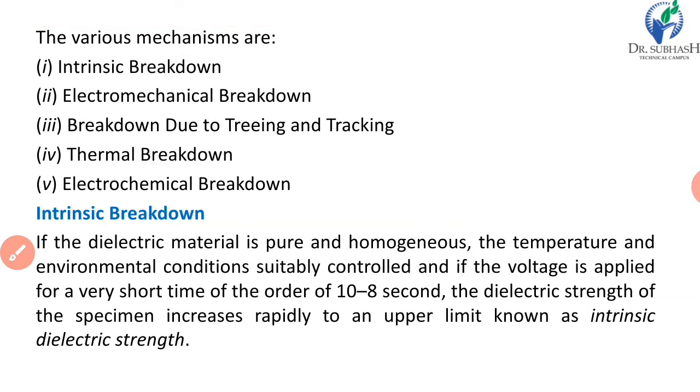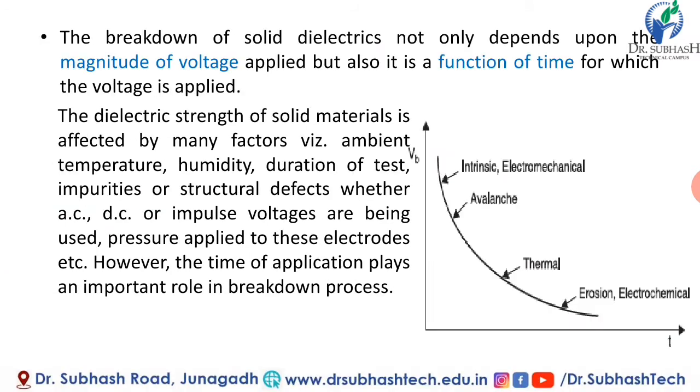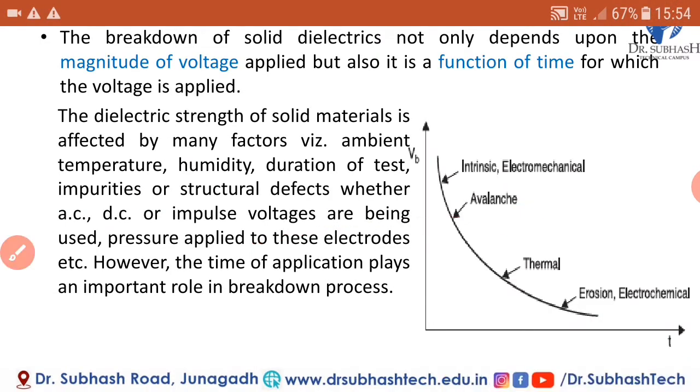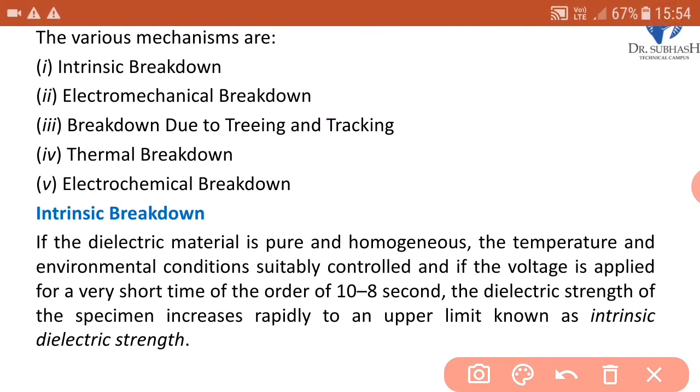The various mechanisms are intrinsic breakdown, then electromechanical breakdown, breakdown due to tearing and tracking, then thermal breakdown and electrochemical breakdown. So these are the various mechanisms. Now we will see intrinsic breakdown.